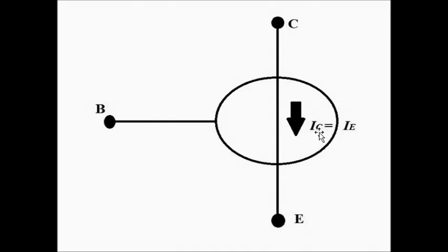As a result, the collector current becomes equal to the emitter current, which is only applicable for the saturation mode of operation. The collector current is equal to the emitter current because of the short circuited PN junction diodes, which create a shorted path from collector to emitter terminal. Again, this is only applicable for the saturation mode. So this is the saturation mode of operation of BJT.